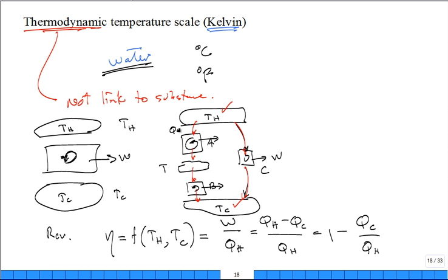I'm going to call this Q1, Q2. But that Q2 is going to be what's coming out because this is just a temporary thermal reservoir which is just going to pass it through, okay, at some intermediate temperature. So what comes into this one, the intermediate temperature thermal reservoir, Q2 from the first heat engine A, is what goes out to heat engine B. And then this is Q3. And for comparison, we just have over here, this is the same Q1, isn't it? Same Q1. And that has to be the same Q3. All right? Same left-hand side, right-hand side have the same thermal efficiency. You feed it the same Q1 at the top, you're going to get the same Q3 out at the bottom. All right.